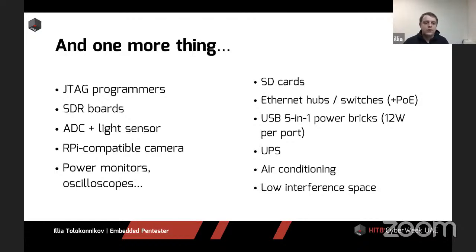Analog to digital converters and cheap light sensors are pretty much everything you need to run cheap tests with anything that involves light. Say you're developing a smart light bulb, or you need to check whether the indicator on your device is lit when you do some action to it. We tried cheap and expensive light sensors too. Both were noisy enough to be a bit unreliable, but not so noisy that we cannot calibrate them. And ADCs, 8-bit, 10-bit, 12-bit, it doesn't really matter.